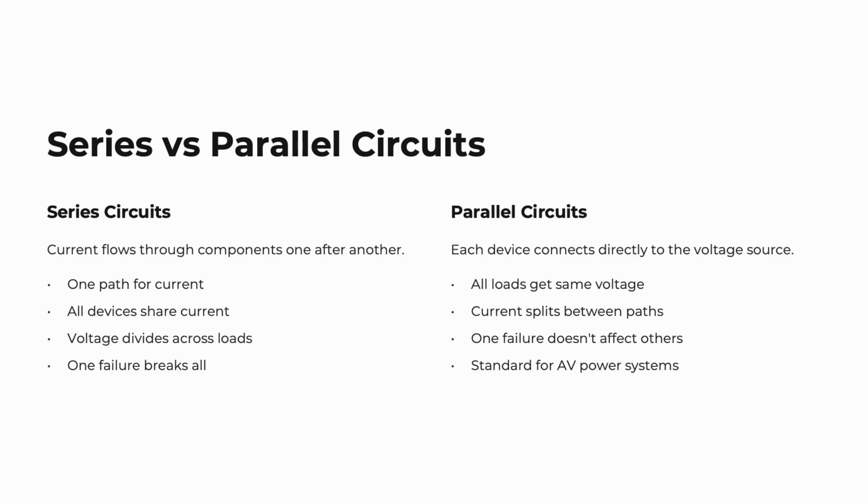This is why load balancing matters. You calculate current for each parallel branch and make sure the circuit can handle the sum of those loads.